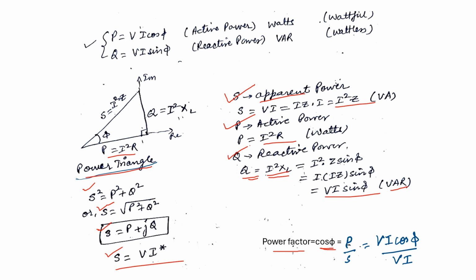The allowable output of such apparatus is usually limited not by mechanical stress but by temperature rise, and hence by the losses in the device. The losses are determined by the voltage and current and are almost independent of the power factor. Thus, the amount of electrical equipment installed to supply a certain load is essentially determined by the volt amperes of the load rather than power alone. The rating of a machine is defined as the maximum apparent power that it is designed to carry continuously without overheating.